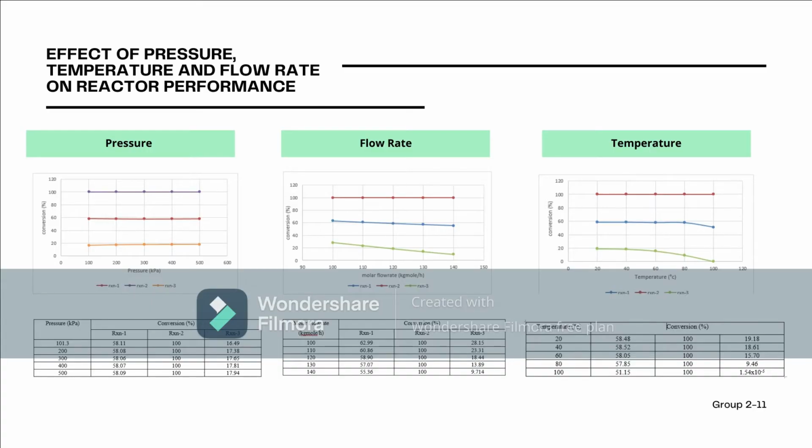To carry out sensitivity analysis on the simulation, pressure, temperature, and flow rate were manipulated at the inlet stream. The data from HYSYS software is obtained and recorded. In sensitivity analysis for pressure, it was observed that there were no dramatic changes to the conversion performance as the pressure was manipulated. It is assumed that there were some errors in the simulation as we are not able to see pressure effect on the conversion.